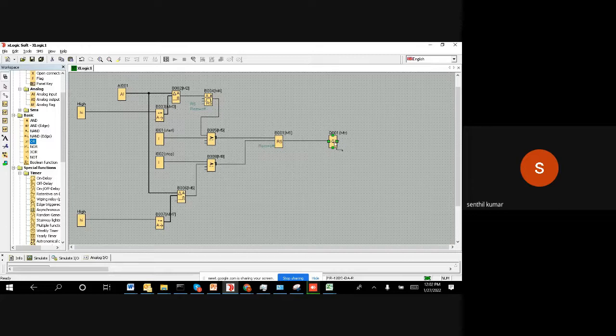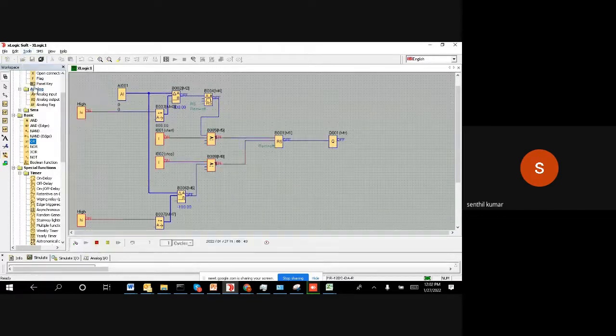That's it. So now this is my preliminary implementation, but there can be something wrong, I'm sure, in the comparator, but I want to simulate and test it. Right. So basically, if my level goes more than 800, I want to start. Okay, start looks to be okay for me. That's correct. I'm trying to come to the stop. Let us see if my level is less than 100, I wanted to stop.